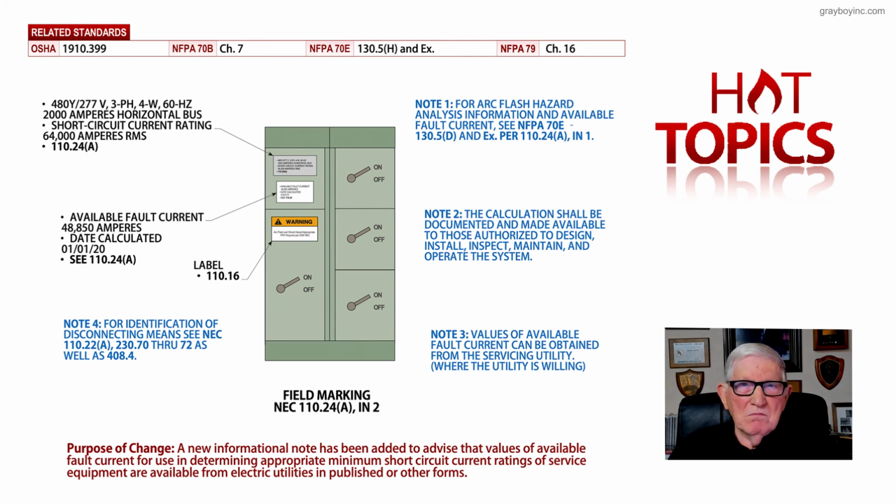So to me, that means they provide the money there, or they put it in a spec with the engineer to maybe the contractor provided or whoever. And notice every 5 years this label has to be visited and made sure that nothing changes that could cause the electrical arc condition to be more severe.